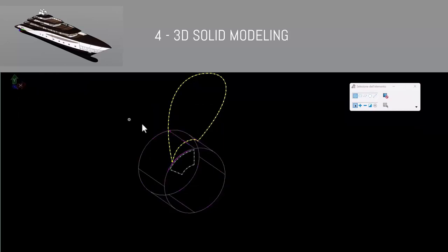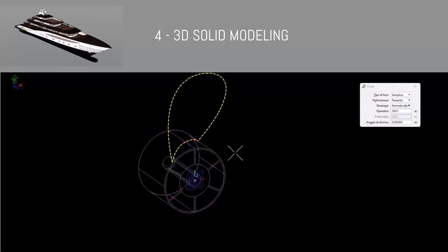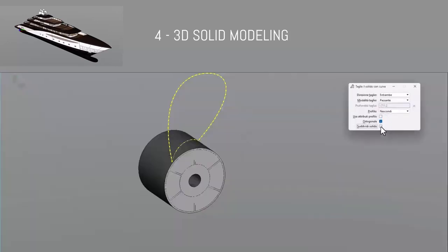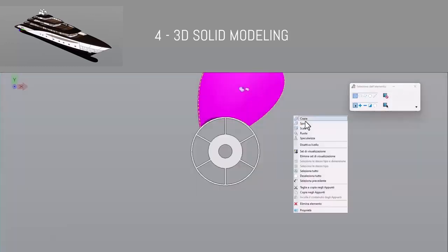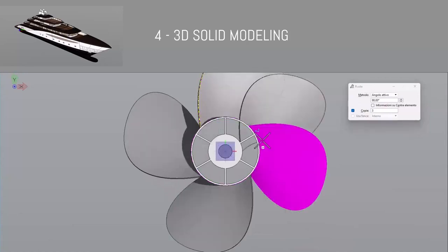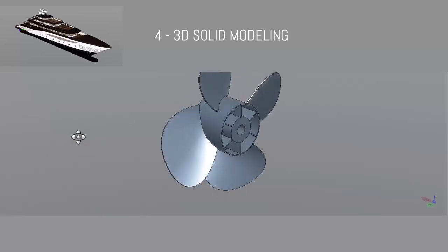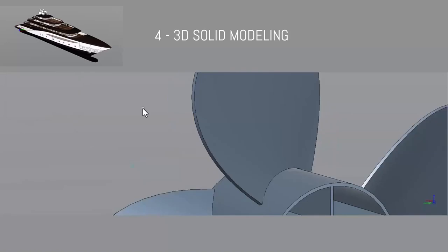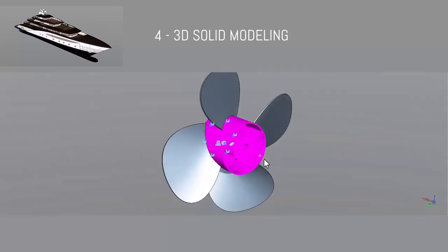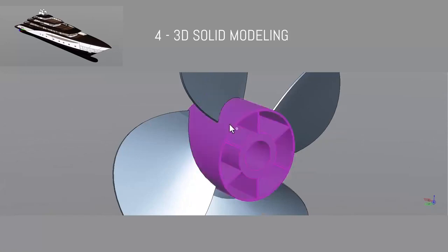We have seen until now how keeping total control of the modeling of curves and surfaces is fundamental in a complex design such as a yacht. Even a specific solid such as the propulsion helix must be conceived as surfaces and then be solidified with MicroStation's parametric 3D tools. In the video, you can see how to multiply the components with rotated copies, applying Boolean modifications, all while preserving the hierarchies of the features, always with permanent access to the parameters and the possibility of revising them.